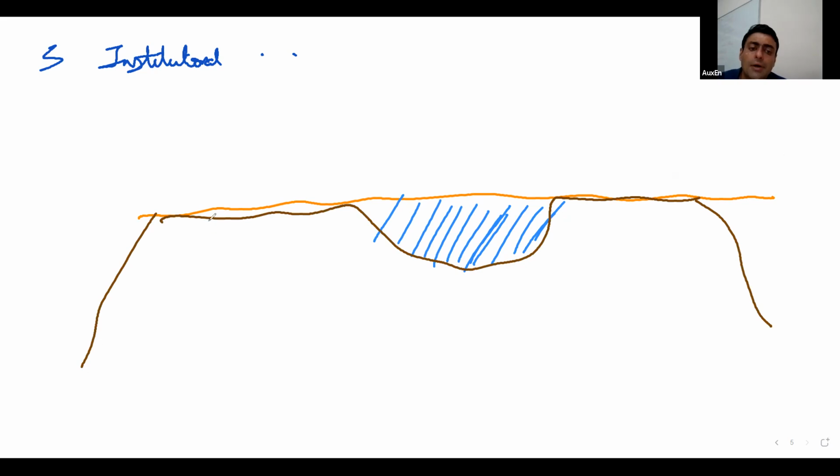Here they had to provide a road, and the road requires certain thicknesses, depth and layers, as you know. So they had to further blast another 600 to 800 mm of hard rock just to accommodate this road. Why did all this happen? Because whoever was doing the master planning of this big institutional building decided not to respect the terrain.